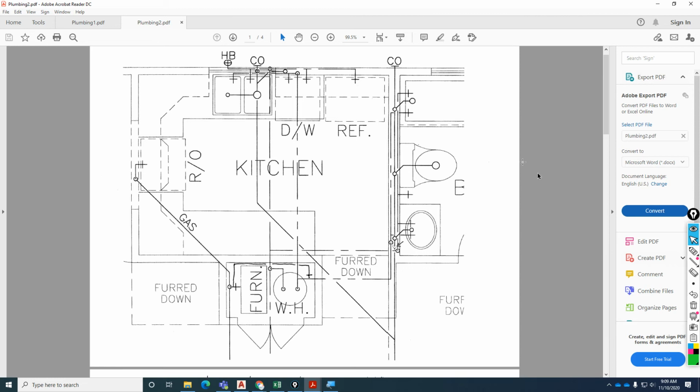Okay, so we have a vent pipe. The vent pipe is connected to the sewer line. We kind of go in here. This is the drain for the dishwasher. Sewer line comes into the vent pipe. And then we have a clean out over here at the back. We have a clean out, okay? So this clean out is a little bit different in that this is a wall clean out.